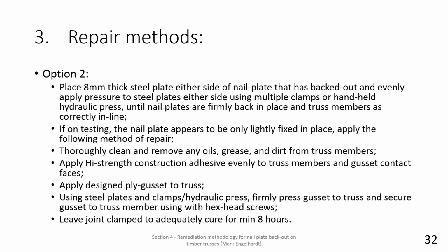Option 2, on the other hand, is a more in-depth and somewhat parasitic structural remediation method that involves the appointment of an engineer to design and prescribe the installation of plywood gussets that will supplement the faulty, deficient nail plates, ensuring the transfer of forces into the appropriate members. The installation shall be carried out by a suitably qualified contractor, preferably a carpenter.